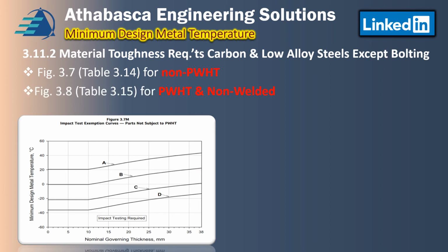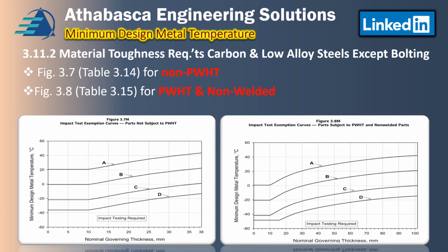And we'll compare those. So 3.8, or equivalent 3.15, is for post-weld heat treated and non-welded parts where you don't have these residual stresses or they've been removed. And so you can compare those parts against non-post-weld. You can see over here that your curve D is about minus 38-ish, but look at where your curve D is here.